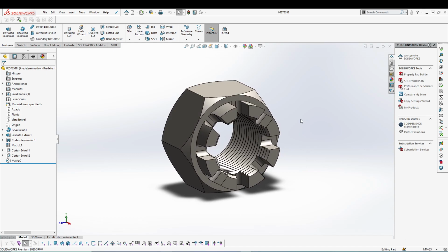So there is a tip: you can create your own view orientation and then save it so that you don't have to make it every time, and you don't need to do it from the beginning. You can save it, and then whenever you want to see the view, just click, just like all these other views that are already there. So to do that, I'll just go to my orientation, select new view over here, and then it will ask me what my name is. So I'll call this close to isometric because it's almost isometric, but I have tweaked it a little bit.